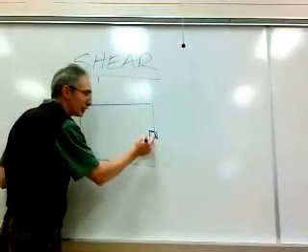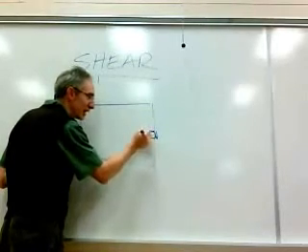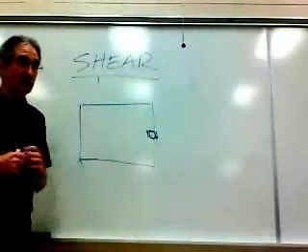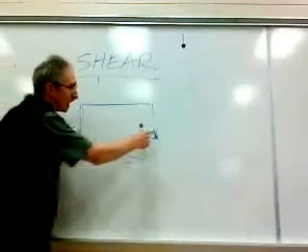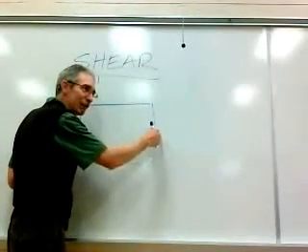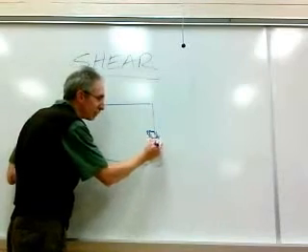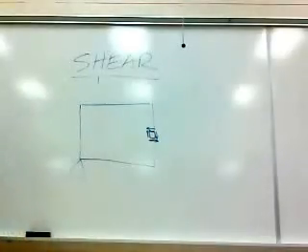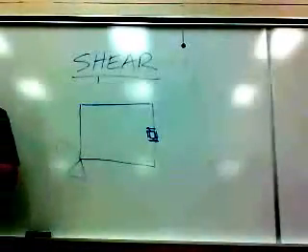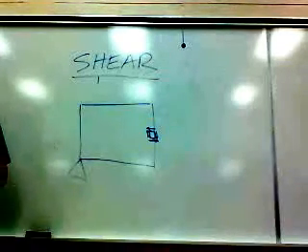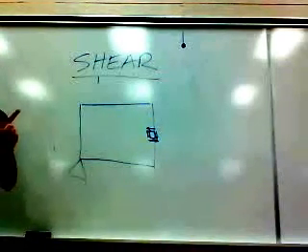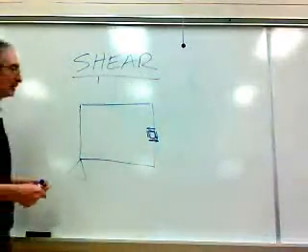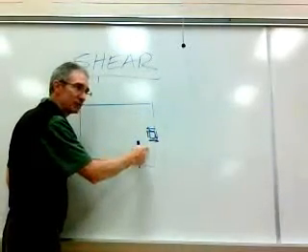Well, if that happens on that piece of concrete, on the other side of that little piece of concrete there has to be a corresponding stress, right? Same, equal and opposite stress. But on that little piece of concrete, you can't just have vertical shear stresses. You've got to have corresponding equal and opposite horizontal shear stresses, right? So this little piece of concrete that we just picked out at this section has vertical shear stresses on it and also horizontal shear stresses on it. They're all going to be equal, right?